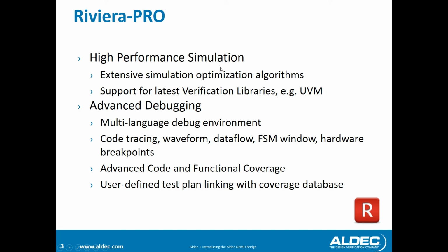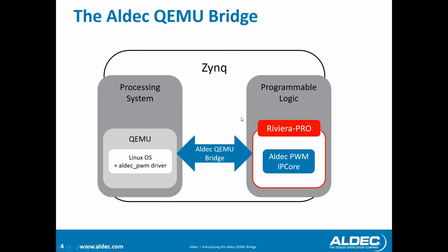This tool will provide the hardware debugging capabilities, such as logged waveforms and hardware breakpoints, similarly to how QEMU will be providing the platform for our software component of the design. Using both tools, that is Riviera-PRO for the programmable logic and QEMU for the processing system, along with the Aldec QEMU bridge between, we can fully model a complete Zynq SoC, allowing us to perform powerful co-simulation of our design.